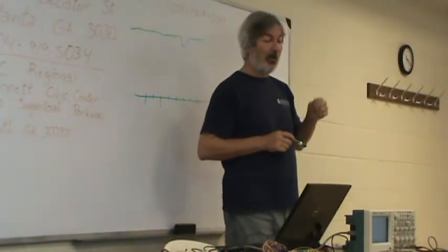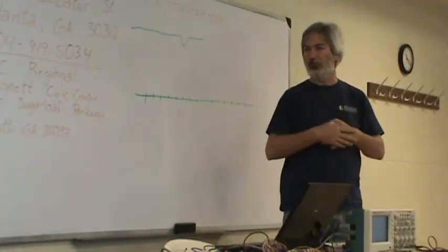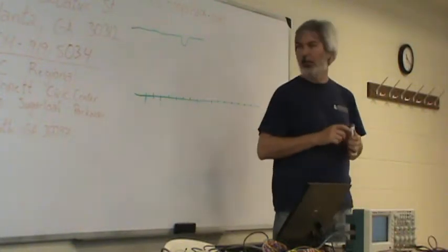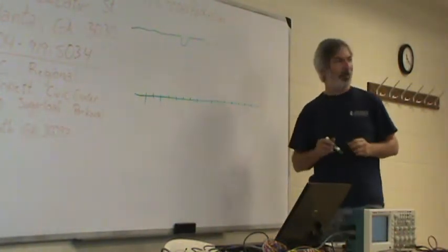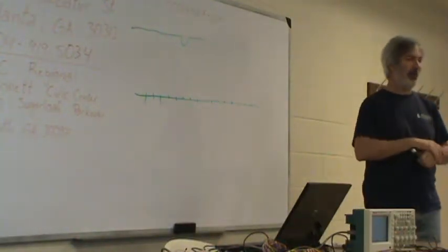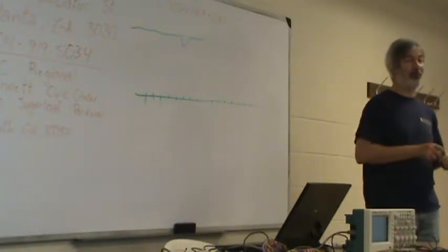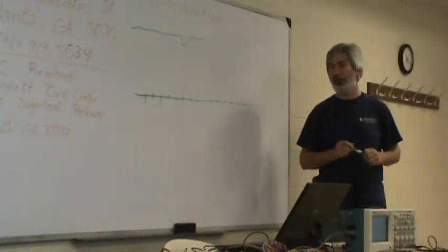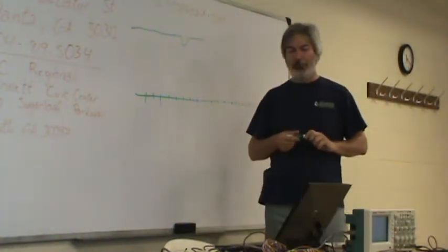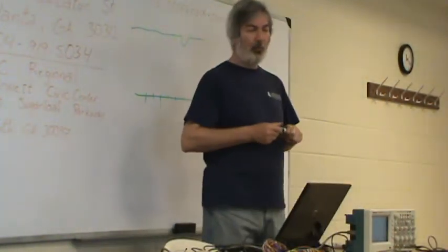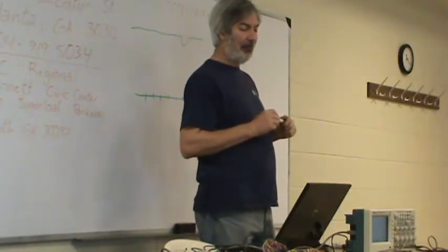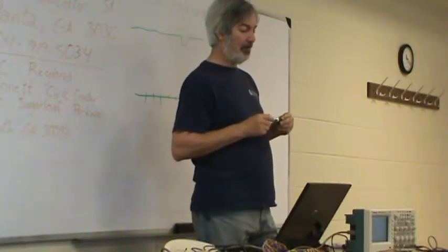And I finally got it sorted out with the help of a website whose name unfortunately has escaped me again. But they had a wonderful little graphic on their webpage. And I encourage everybody to go and Google oscilloscope aliasing because it has a lot more detail than I will be able to provide here. But aliasing comes up as a problem when you have the time base of the scope set wrong, because you can end up having a signal that looks different from what it really is.